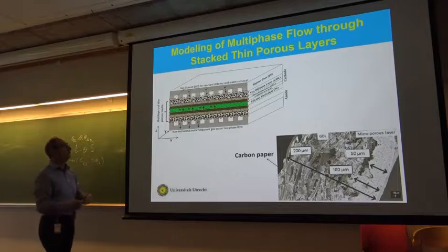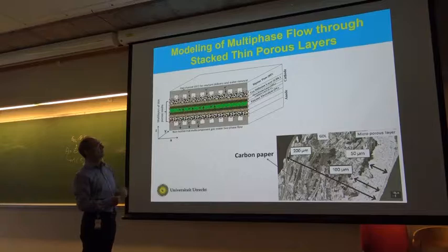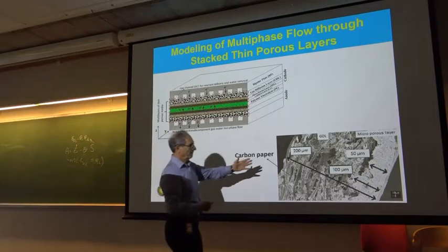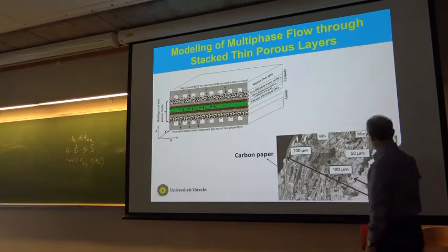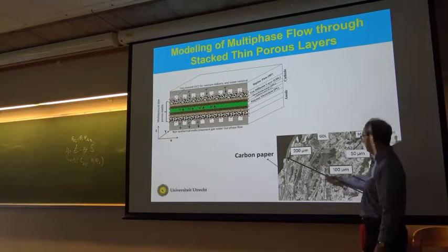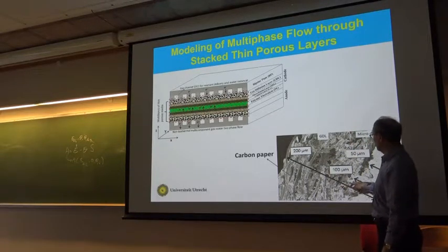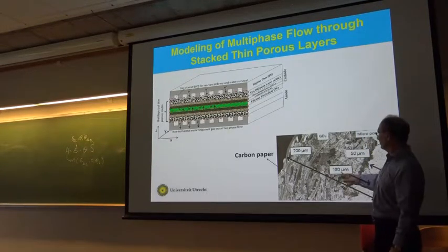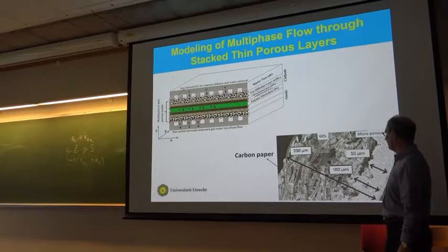So you know, fuel cells are also layered, and all kinds of hydrophilicity and hydrophobicity are involved. Some of the features of these layers, for example, this is the gas diffusion layer, this is the macroporous layer. In all these cases, the thicknesses are small. For example, the gas diffusion layer is about 150 micron in thickness. Macroporous is about 50 micron.